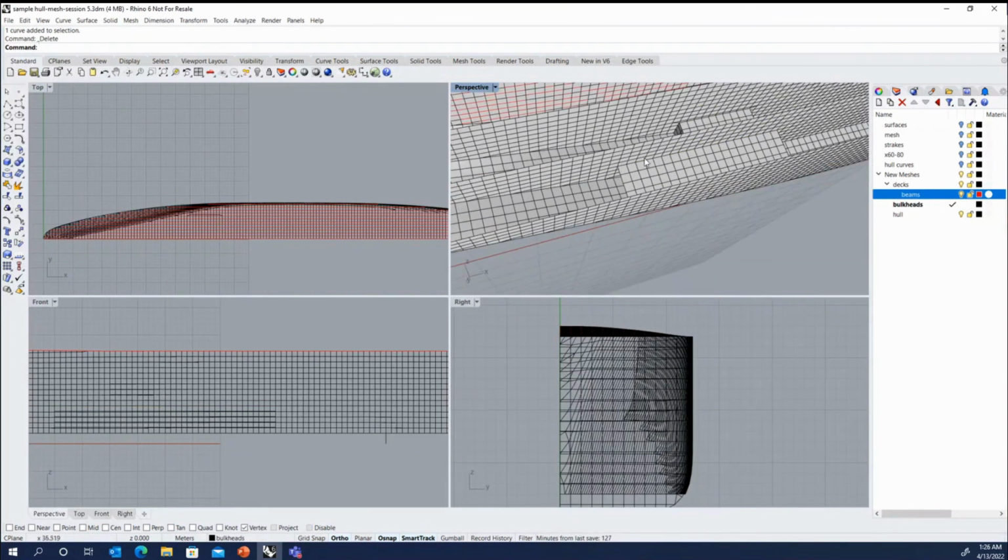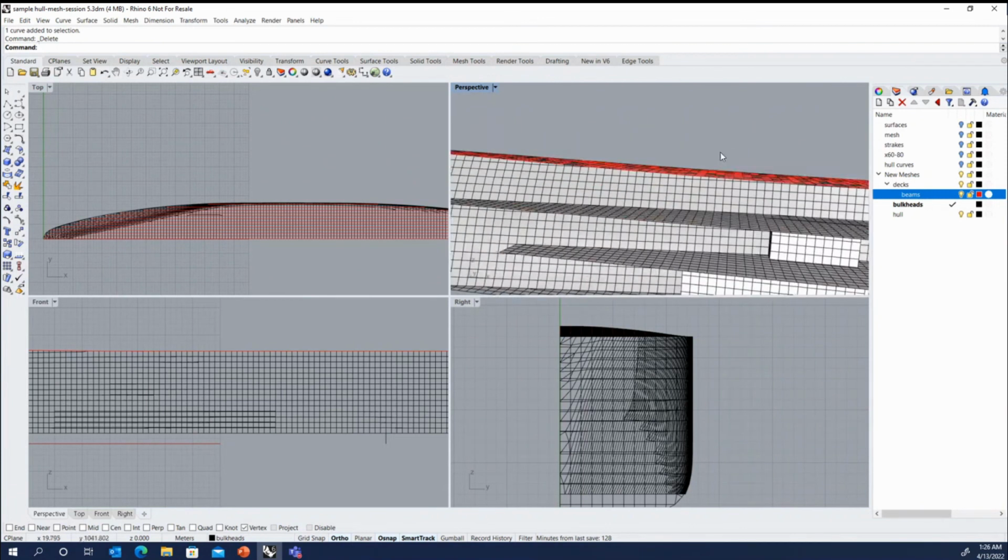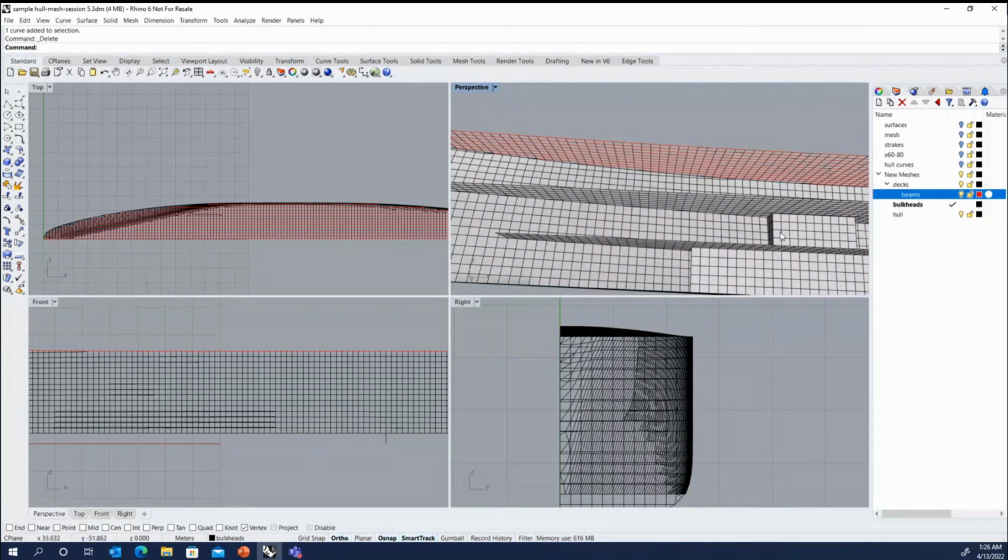You could also delete all of these curve points that interfere with the bulkhead so that you'd have the appropriate polyline coming back to the beginning of it, one long segment along the length, and then the rest of the polyline aft, and then do the explode, unselect, and join, and then delete that one long polyline. There's a couple different ways of doing it. It's whatever personal preference, but it's sometimes easier to modify these beams before you export them.